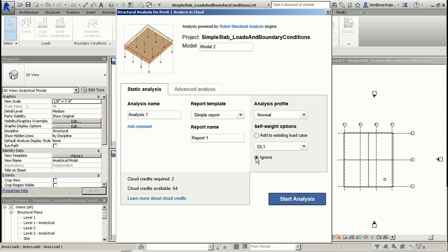Yes. They're exposed through something called the results builder, which is part of the SDK. So if there's results packages that get stored back in Revit, you can then read those results packages, read the contents of those result packages to do any analysis or design that you want. You could drive them into your Excel spreadsheets, or iteratively drive them in, or whatever you want to do. So those will be available.